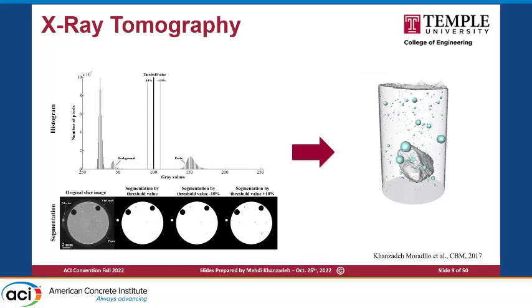After imaging, we have to go through different processes to analyze the images, the reconstruction. Here I'm showing an example of the air void filling phenomenon. Starting from the left with the control sample, over time we have a salt solution on top of the samples, and we monitor how the air voids get filled with the salt solution or any salt deposit. We can do this reconstruction to get an idea about different features: the distribution of the air voids, the aggregate, the interface, and so on.